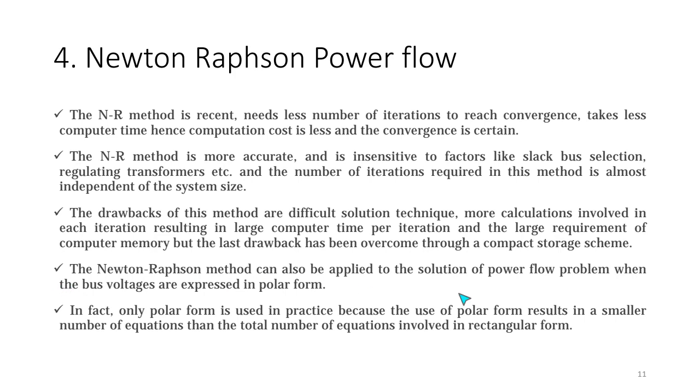And the Newton-Raphson method can be applied to the solution of the power flow when the bus voltages are expressed in polar form. You remember I spoke about the Newton-Raphson method, we need to express the bus voltages in polar form, not in rectangular form. And only polar form is used in practice because the use of polar form results in a smaller number of equations than the total number of equations in rectangular form.